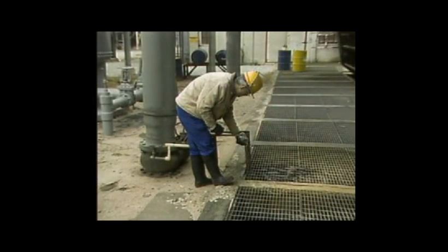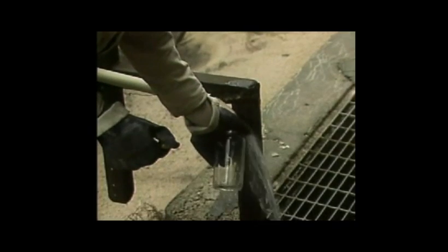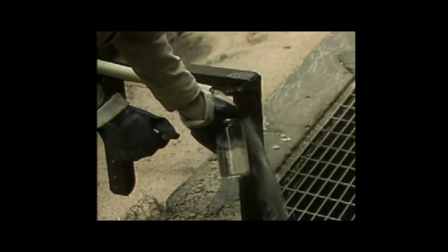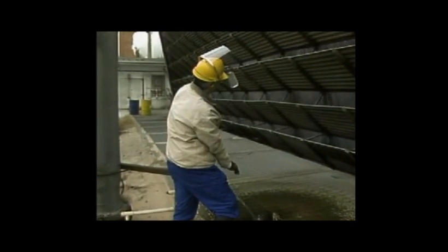Cooling water is often sampled and tested for solids concentration and pH. The results of the tests determine how often blowdown should be done, how much water should be blown down, and the amounts and types of chemicals that should be added.